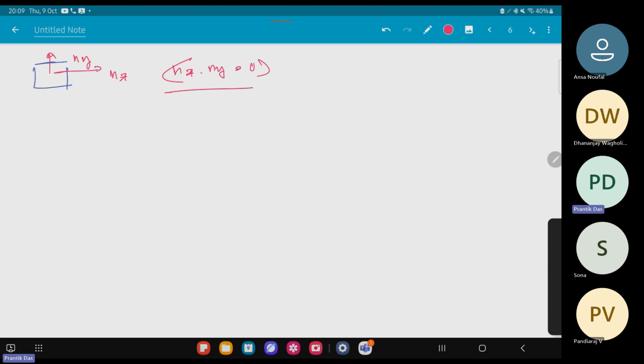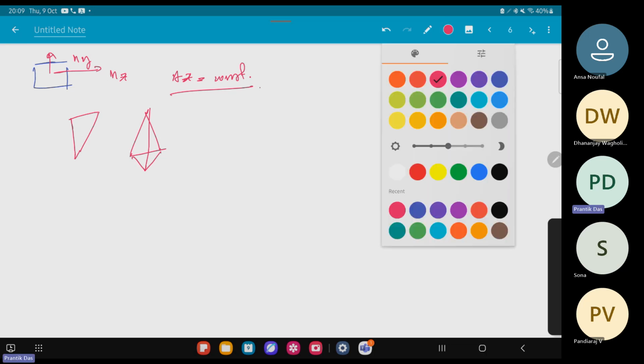And also we are going with the uniform grid itself, where delta x is the same over the whole domain. That is constant. And now we are going to the unstructured grid. So an unstructured grid typically looks like triangular grids if it's a 2D one. It looks like a tetrahedron if it's a 3D one. So these are unstructured grids.